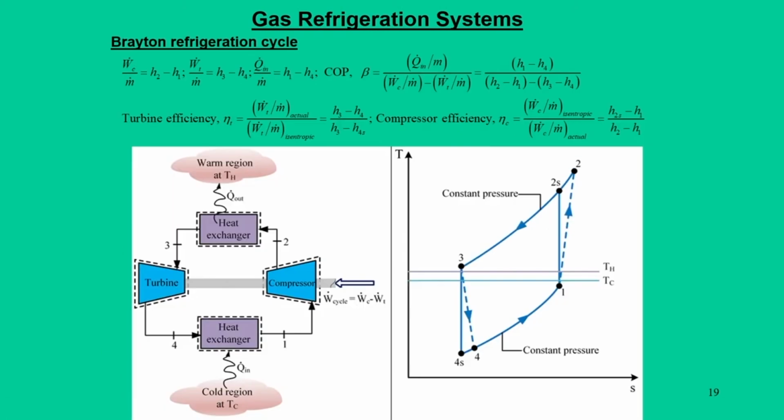One important thing I want to point out is that when you talk about air cycle refrigeration, it gives the desired cooling effect, but it is very difficult to cater to the need for a subcooled region temperature below 0 degrees centigrade using gas cycle refrigeration. So, it is normally used when the temperature in the cold region is not significantly low.